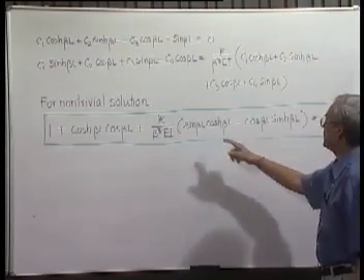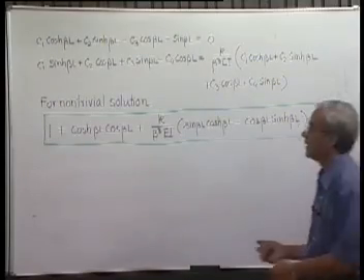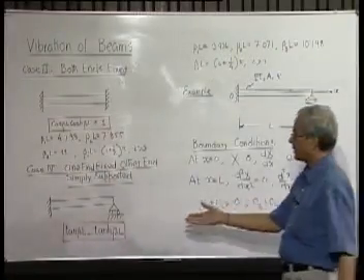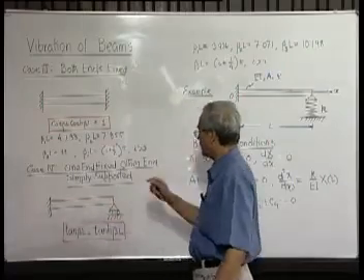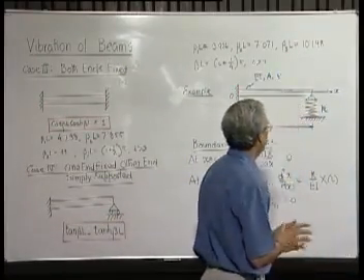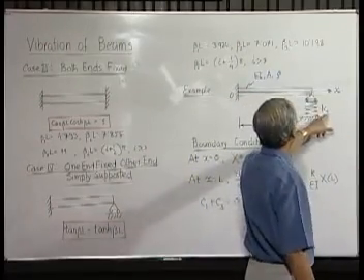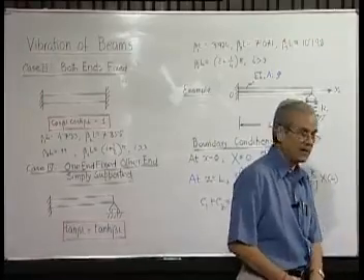So, sin beta L cosine hyperbolic beta L must be equal to cosine beta L sin hyperbolic beta L, or tan beta L equal to tan hyperbolic beta L. That you can see is the case where one end is fixed, one end is simply supported. So you can see the limiting cases are being satisfied, but otherwise the solution will be possible only when k is given and all other numerical quantities are prescribed.